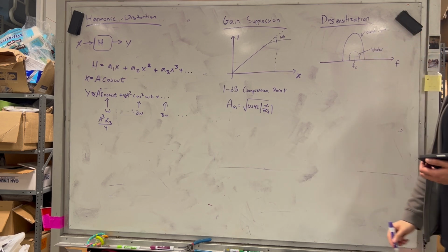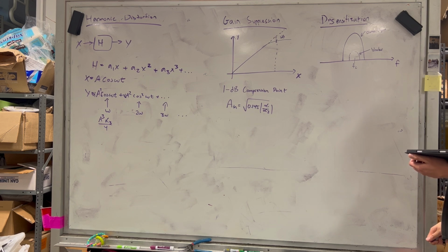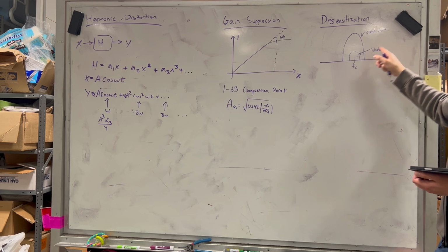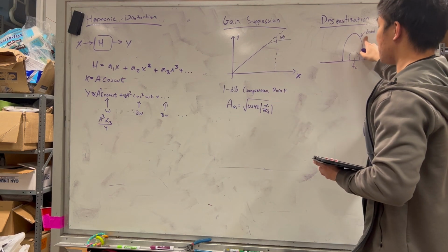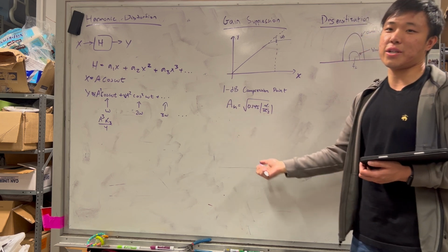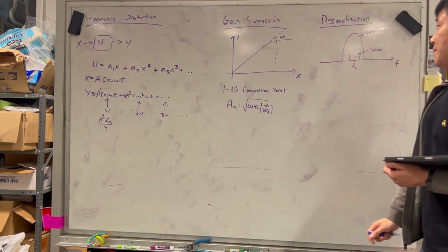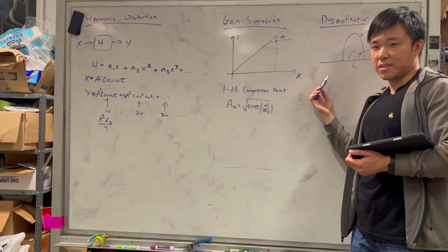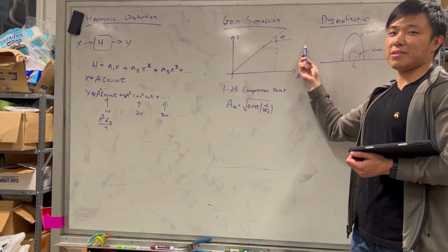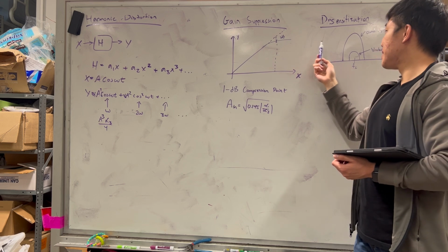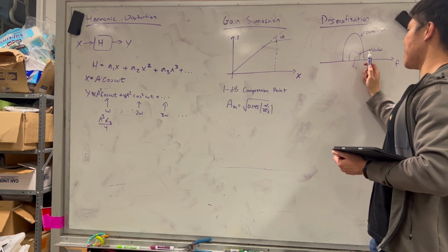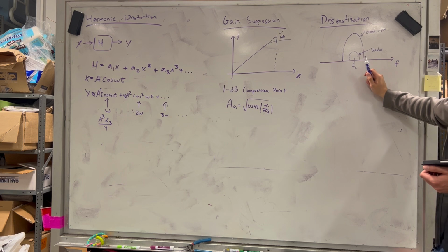We can deal with this, right? Well, we have to do some work to fix this, but we notice that we have some spectrum of blocker that's blocking our desired signal here. Now, what happens when this is so large that it goes through a system that experiences gain suppression? Looking at the graph here, if this is really far in, it won't get amplified at all, because you're suppressed already. Whereas this signal, if it's down here, will get amplified. So your sensitivity goes down and your SNR gets worse, right? Does that kind of make sense?